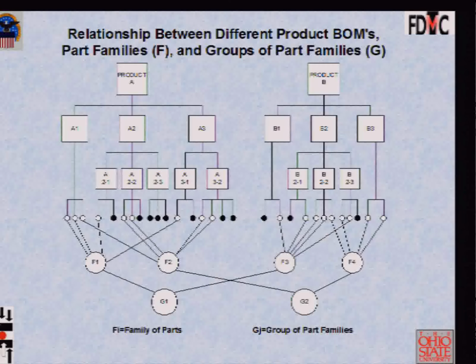Now, the holy grail. How do you extend this method to multiple bills of materials? We haven't yet gone there. We know how to do it. Effectively, it would be multiple value network maps. But again, how would you do it? This came out of Gallagher Knight, 1972 book. So decades ago, the Britishers had figured out that the way you do lean in any kind of high mix, low volume facilities, you take every product, explode it into its components, and run all these components through a group technology part family formation analysis.